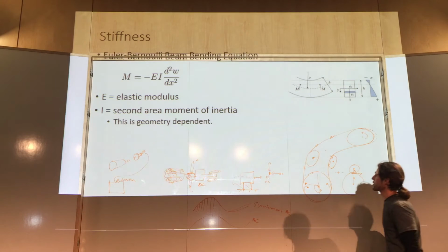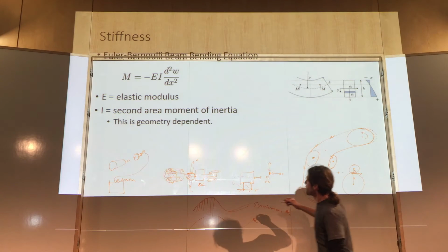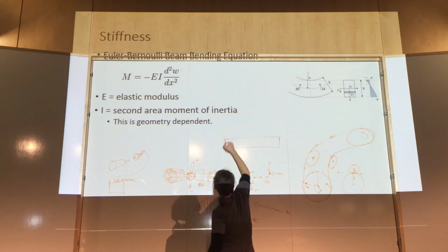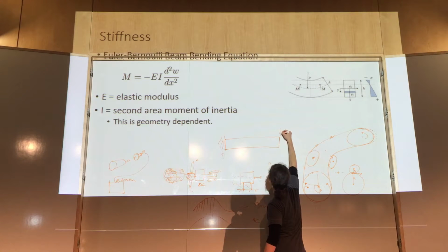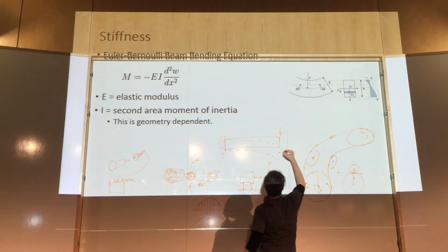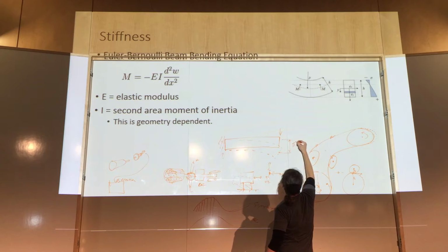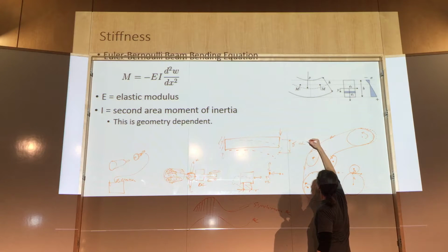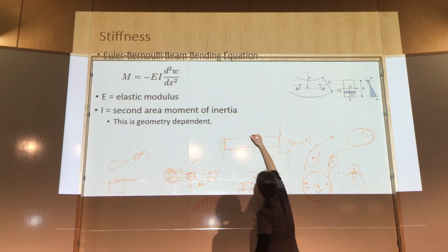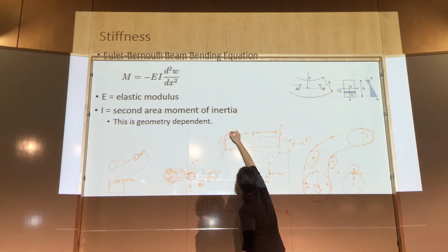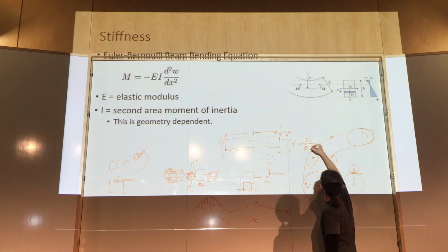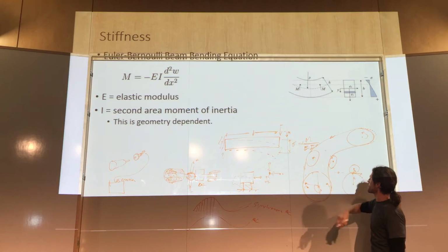And something to keep track of is, say you've got this beam, and it's fixed on one end, and you're applying some load over here. It's going to have some sort of deflection. And this deflection is proportional to your applied moment, or basically this force times some distance here, or it could be just an applied moment, divided by EI. And there's a bunch of other conditions there. That's basically what that equation is showing you.